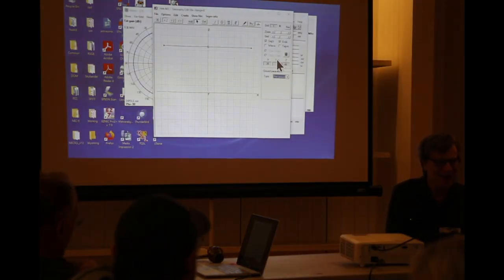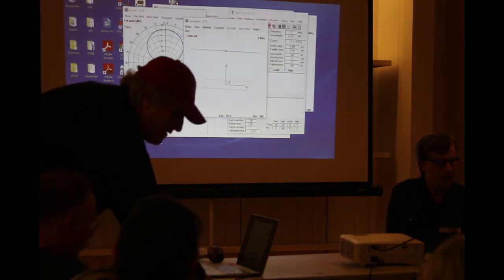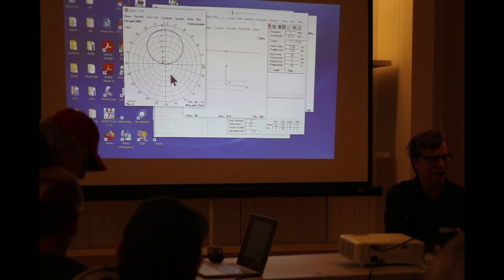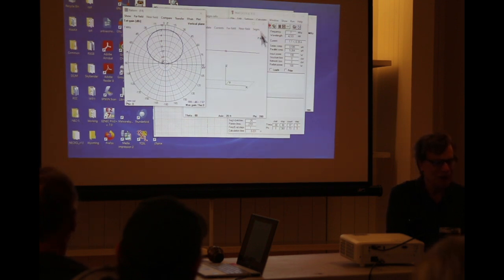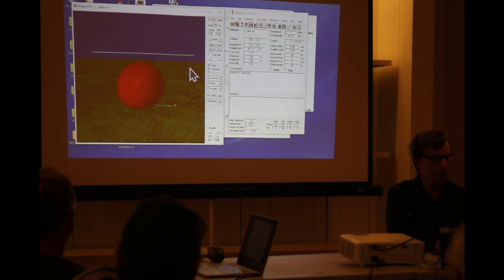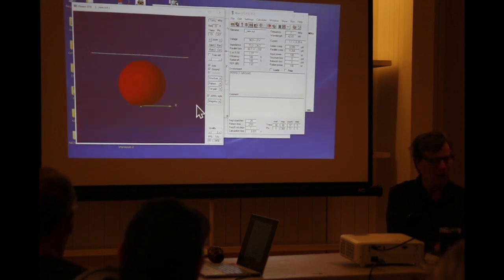So anyway, let's calculate this again. Run through a calculate, far field pattern. And lo and behold, we don't have anything below here, right? Everything's above ground, okay? And we can go to our 3D view again, and go to our pattern. And lo and behold, our donut has now become more like a kidney bean here, okay? We're missing our really nice dip in the middle. But you notice also at ground, at horizontal, we have a perfect null going out horizontally from this, okay?